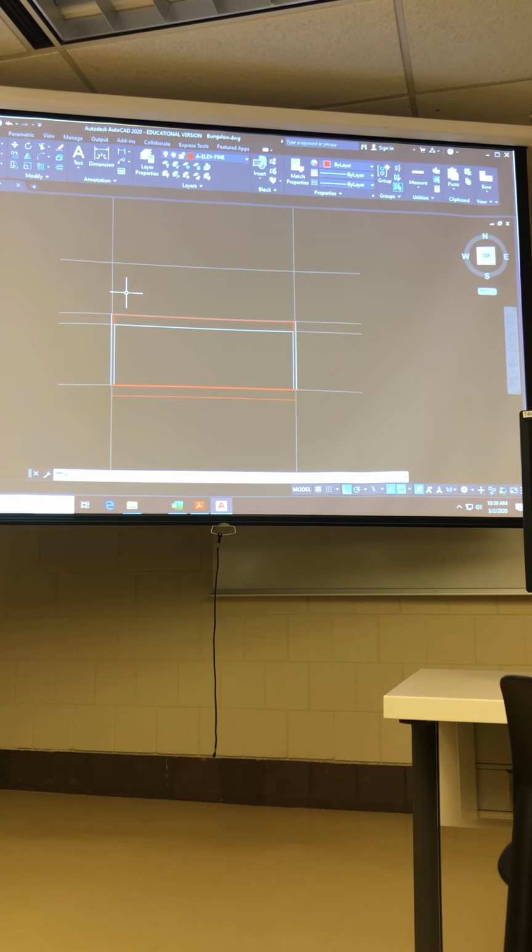I'm ready to mirror. So I'm going to draw from that construction line, that's the middle of the room, the middle of the house, and there's my roof structure. And then I'll go ahead and just use chamfer, and we'll clean up all of these lines up above. We'll join that.